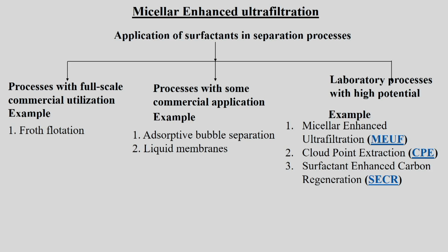Then we have discussed in detail about the micellar enhanced ultrafiltration, where if the surfactants are solubilized over their critical micelle concentration, then micelles are formed. Then these micelles will be able to trap the solutes and make big globules. Okay.